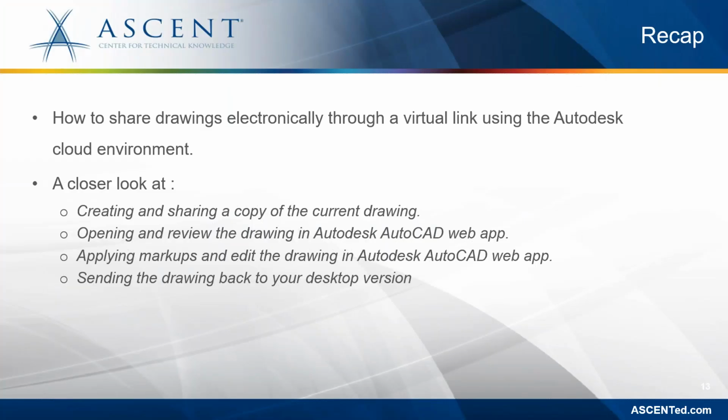It was how to share drawings electronically through a virtual link using the Autodesk Cloud environment. And what we were able to do today is create and share a copy of the current drawing. We were able to open and review the drawing in the Autodesk AutoCAD web app. And then we were also able to apply markups and edit the drawing in the Autodesk AutoCAD web app, and then send the drawing back to your desktop version and do whatever you needed to do in there. Then it's the normal process again.